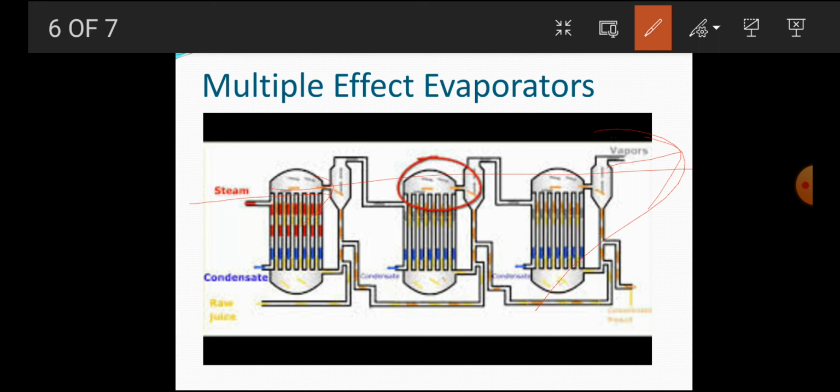On the other hand, this method is not suitable for cold feed because the steam input in effect 1 raises the temperature of the feed, and only a small amount of heat is supplied as latent heat of evaporation. A lower amount of vapor in effect 1 produces a lower effect in subsequent effects. The amount of vapor produced will be less than the steam supply, hence the overall economy is lower.